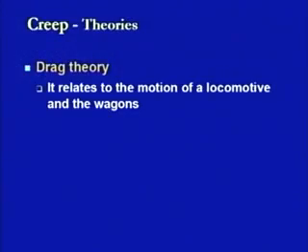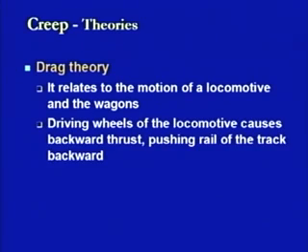Now, another theory related to creep is drag theory. The drag theory relates to the motion of a locomotive and the motion of the wagons. What it tries to say is that the driving wheels of the locomotive cause a backward thrust, and it tries to push the rail of the track backward.